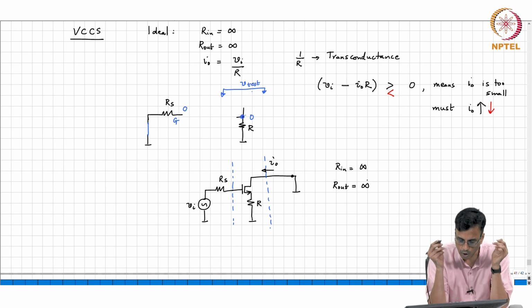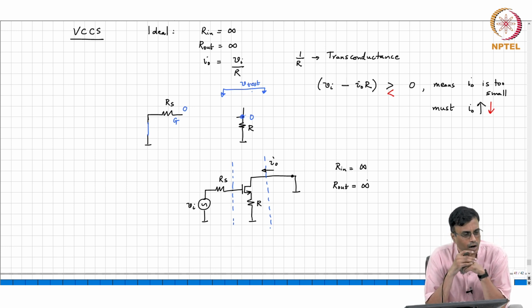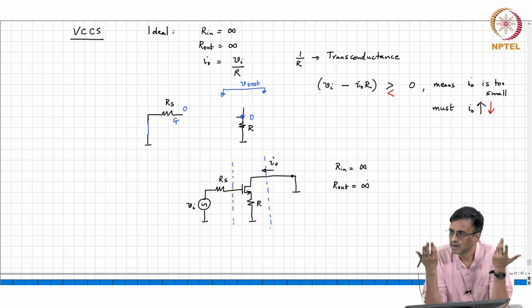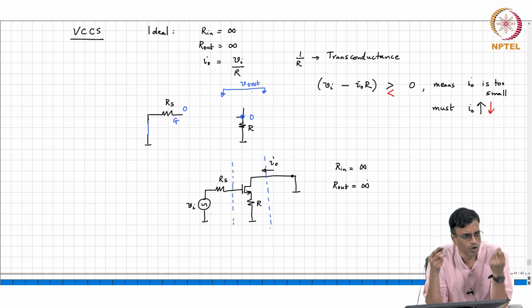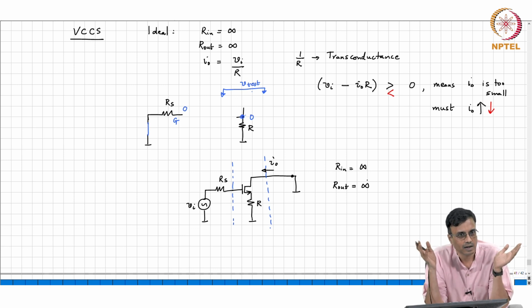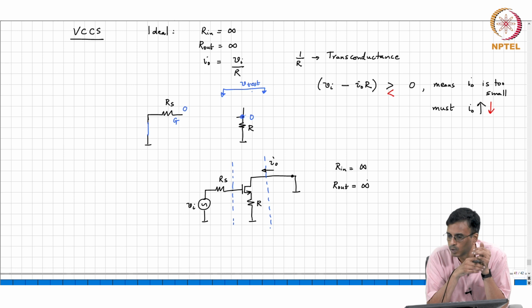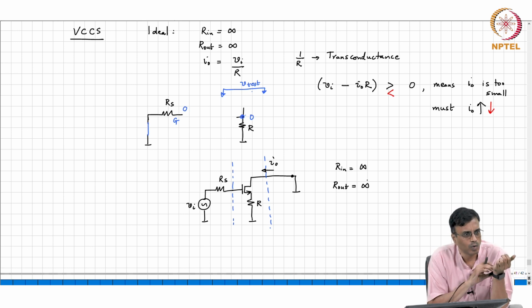In a MOS transistor operating in saturation, what comment can you make about the influence of the drain potential on the drain current? That is all that you need to recognize that the output resistance must be infinite, correct? The drain current of the MOSFET is not influenced by the potential of the drain, period, right? At least in our ideal model of the MOSFET, which only consists of a voltage controlled current source.